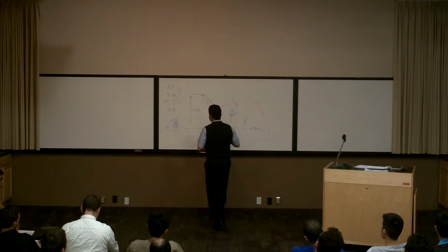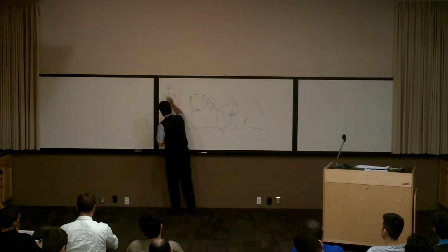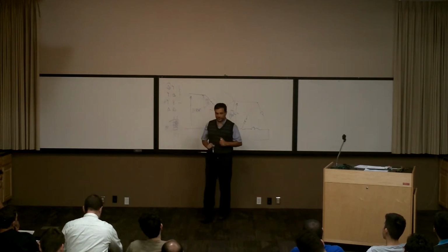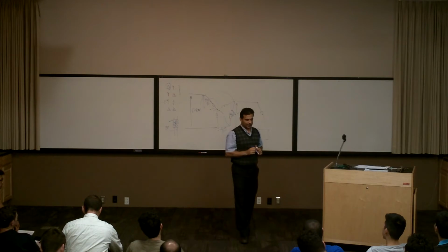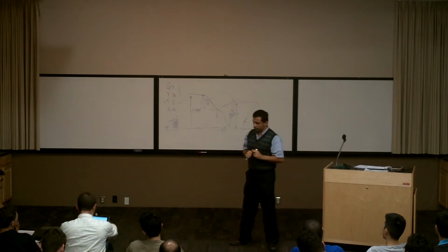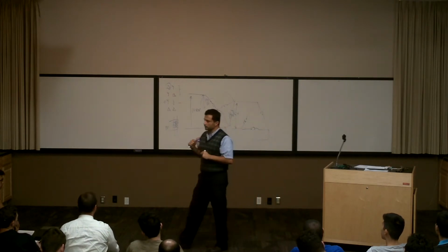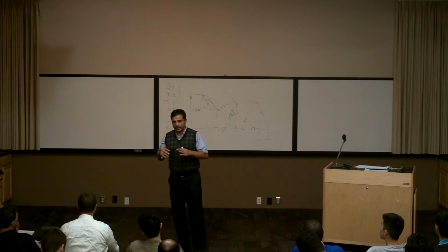What's the advantage of delta connection? I don't want to get into detail, but especially in the generator, delta is a very, very good filter for third harmonics.